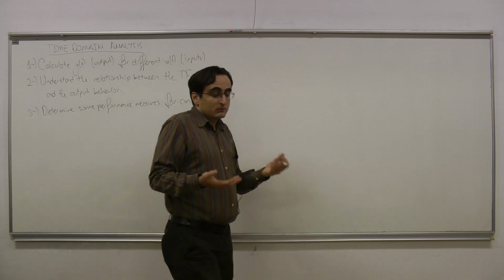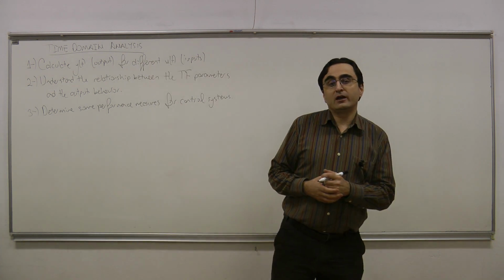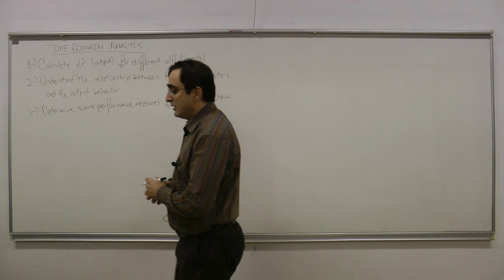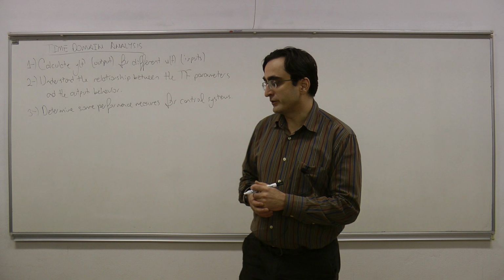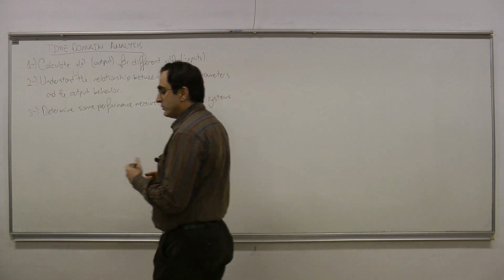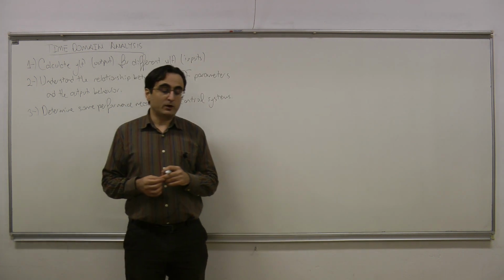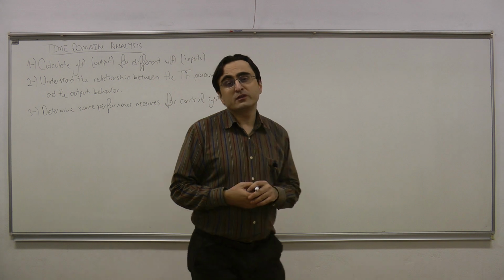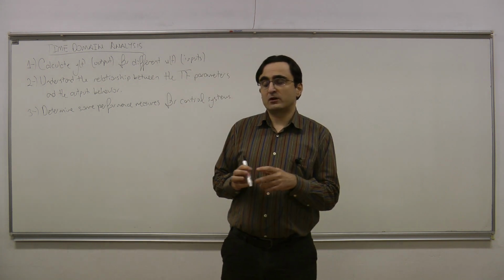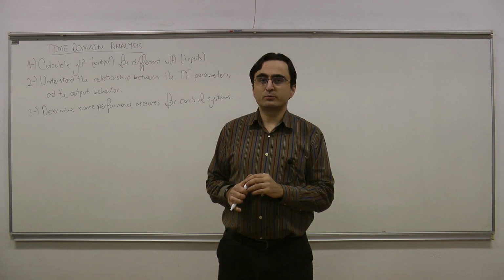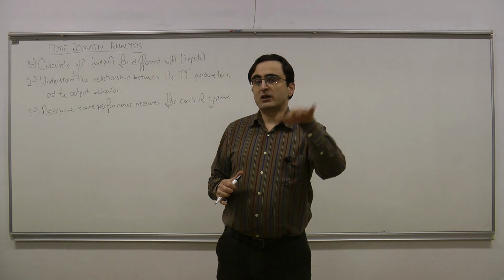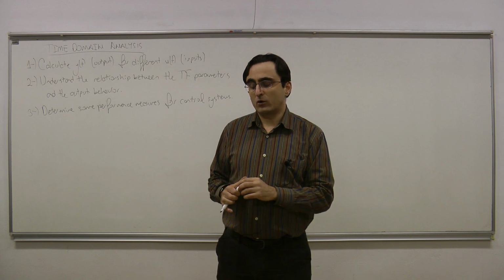So for large settling times we would really not like, and small settling times we would want from a control system. Or there are also other types of performance measures. We're going to see that some control systems or some controllers would cause some oscillations in the output, and we really do not like a lot of oscillations in the output.